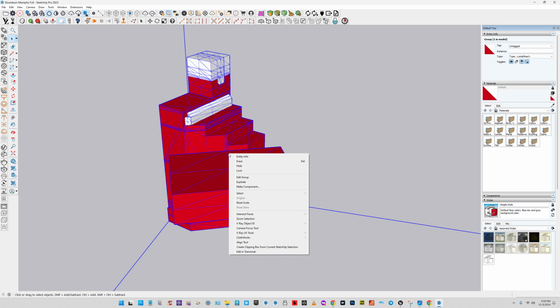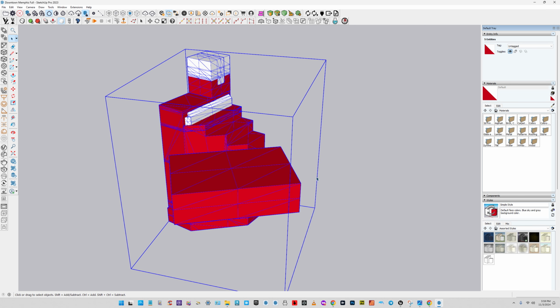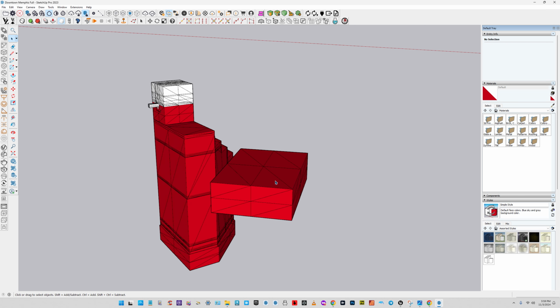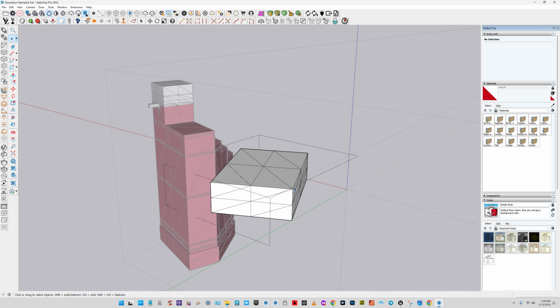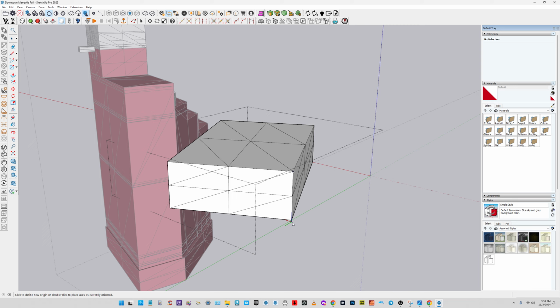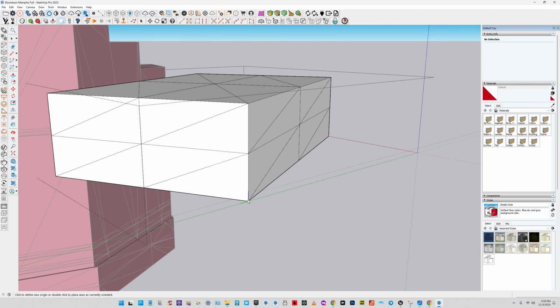Now escape. I'm going to ungroup this or explode it. And we got some assets in here. That's Control R, Control Group, and double click into it, Control Shift A. These are shortcuts that I added, and this helps me change the origin rotation.